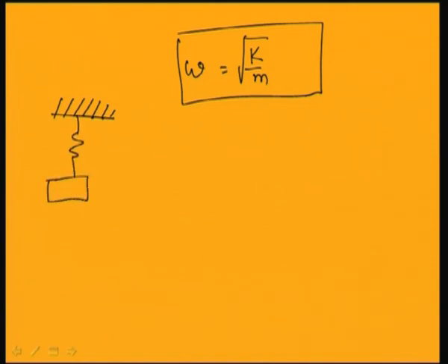So, this is the first spring and mass system, let it be k and m. Let us take the same mass and stiffness. So, this is m and k. In this case I can take the static mode like this. So, this will have a weight of mg and this has a weight of mg. So, 2 mg weight is acting on the spring k. So, it will have a displacement of 2 mg by k.